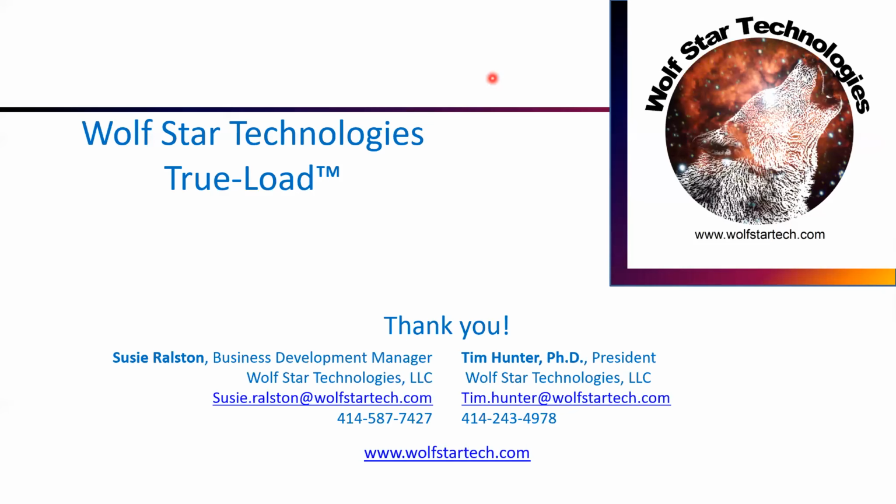But the way we handle contact, and this gets handled very efficiently, is if you've got well-defined contact on your structure, you can put unit loads at the contact location, and then TrueLoad will basically turn those unit loads on when the contact is happening. And if you don't have contact, then the loads from the contact area will be turned off. So we do an excellent job with handling contact.